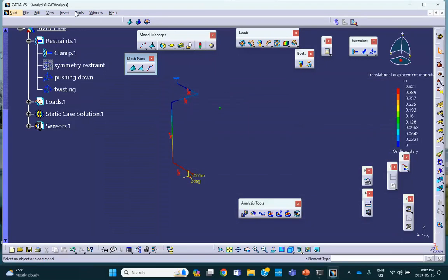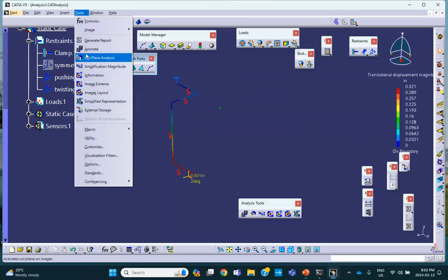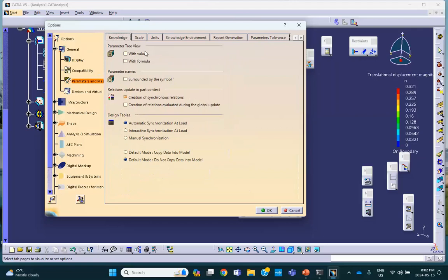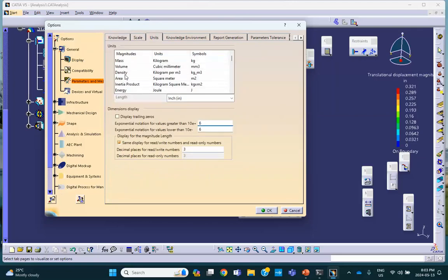So you go to tools. I mean, obviously you can use your hand calculation to convert that, but that's crazy. Tools, options, under parameter measures, under units. Let's find the moment here. If you're having a hard time, click on magnitude so that it sorts it alphabetically. There we are. Moment, I want to change that to pound inch and then say okay.